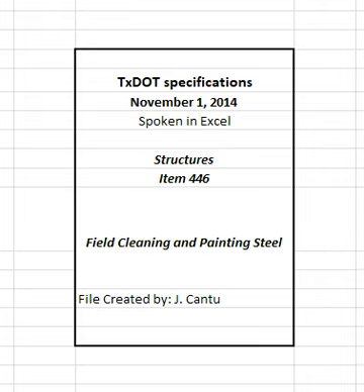2.1.3 System 1I. Provide number 810 prime coat meeting DMS 8100, structural steel paints formula, and acrylic latex appearance coat meeting DMS 8101, structural steel paints performance. 2.1.4 System 1-2A. Provide paint in accordance with DMS 8101, structural steel paints performance. Provide organic zinc, OZ, prime coat, epoxy intermediate stripe coat, epoxy intermediate full coat and urethane appearance coat.